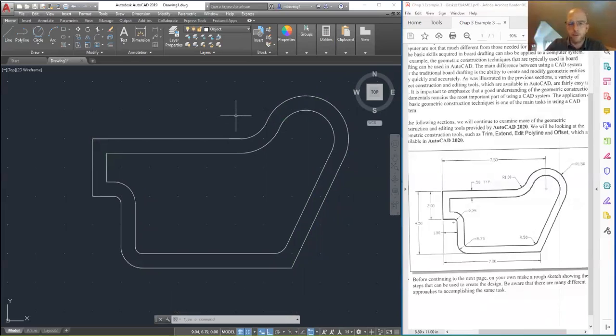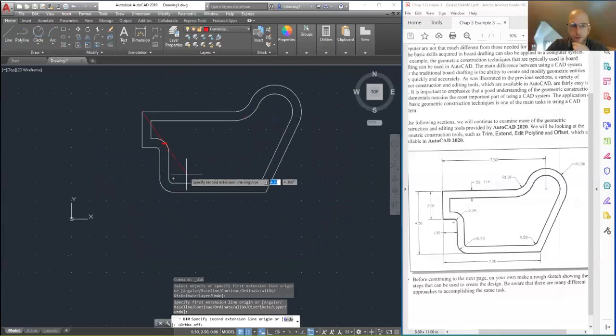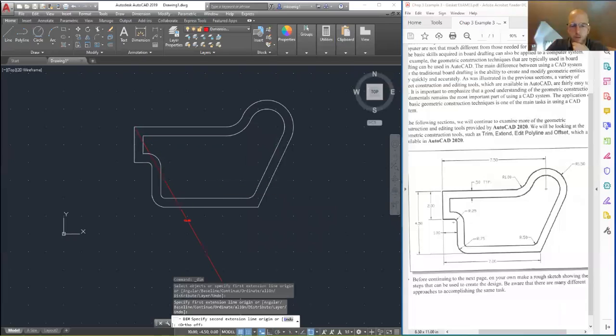All right, next, let's start dimensioning this and put it on the drawing sheet. So I'm going to set my layer to dimensions. And we'll just go through and add these dimensions. Doesn't matter where you start. I'm going to turn off the ortho mode to make it a little easier. Grid snap is still turned on. I'll turn that off.